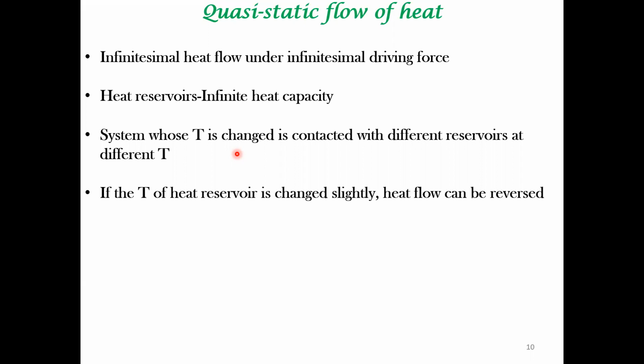So in quasi-static, there are two components. One is infinitesimal heat transfer, and then there is reversibility. What do I mean by that? For example, if I'm removing heat from the system to the reservoir, when the difference between the system and the reservoir is very small, with the system temperature being higher, and I increase the temperature of the heat reservoir to be slightly more, then I can reverse the direction of heat flow.